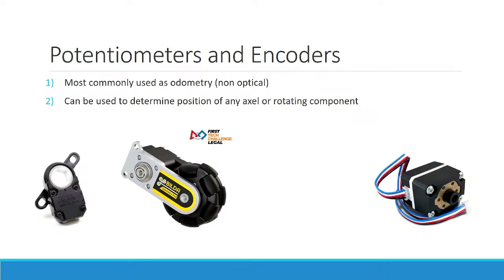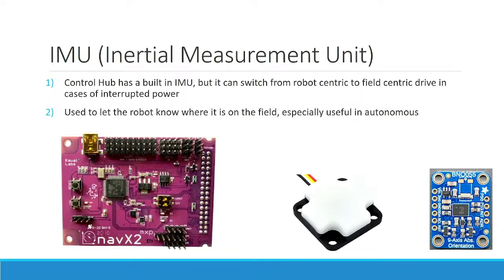So having that information, rather than just relying on a servo, because sometimes if it's a whole big mechanism, you need a DC motor, then that information becomes very vital very quickly. Otherwise, you're relying on positive stops, and you may be overstressing your motors just to try and hit it against the positive stop. And that causes other problems.